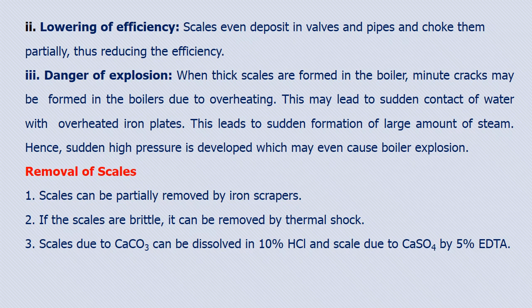When it starts expanding, it gives a crack inside the boiler. That is the scale which is formed, which is not a conductor, so it starts breaking because of the expansion of the metal part outside. Suddenly water gushes into the opened-up part, where the scale is broken, and it is in direct contact with the boiler. Now it is in direct contact with the metal part, which is heated quickly. Suddenly there is an accumulation of steam and it is pressurized.